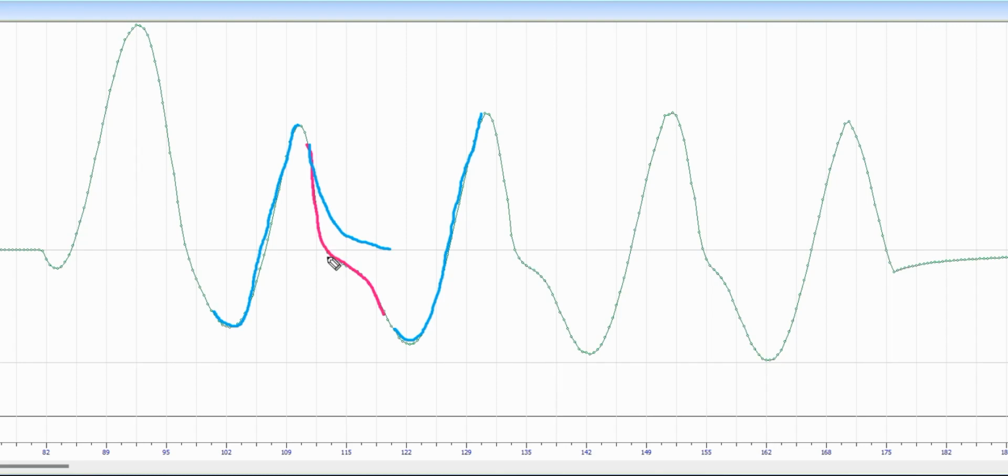Now how can this behavior be explained? The problem lies precisely in the rectangular magnetizing curve. That is, in the last type of the curve that we've explained in the previous video. This type of magnetizing curve cannot guarantee a transition through zero when the current transformer is saturated. Well, what must be done to correct this? We could apply the second type of magnetizing curve. We can try to actually simulate this behavior in the model.